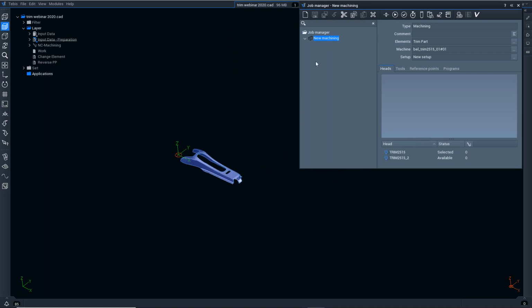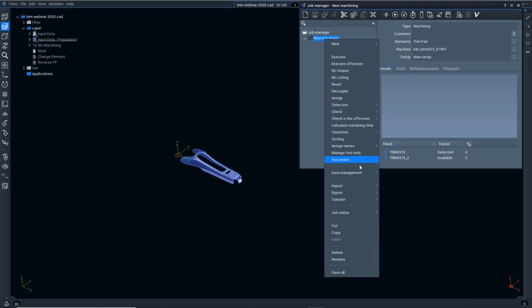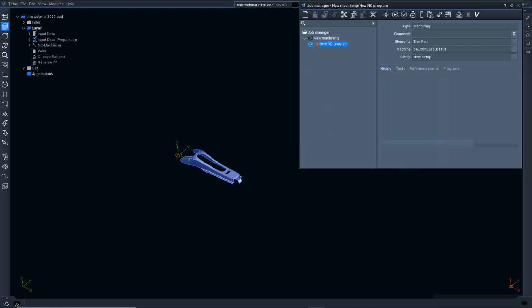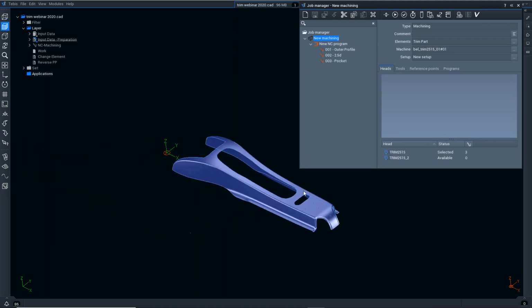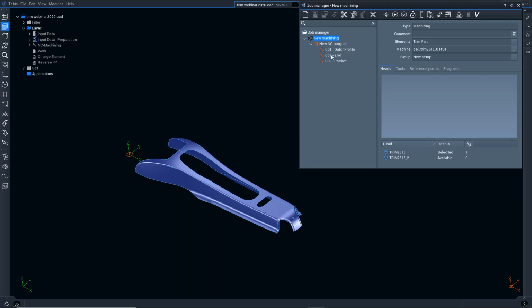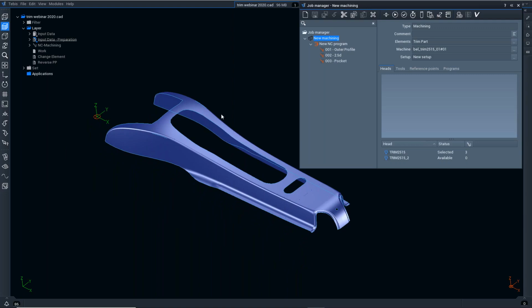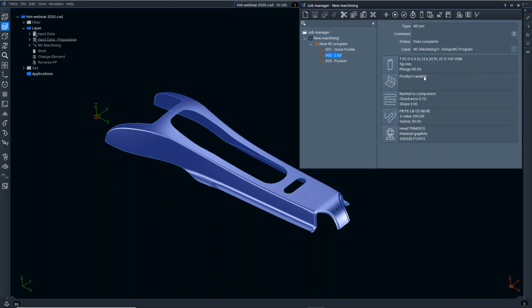What I'm going to use today is a template. So basically all I've done is I've predefined a series of machining operations, which you can see here. And not for the first one, but for the second two, I've had Tebis pre-select the data. So by organizing the data using various colors and positions in the layer tree, I'm able to have Tebis predefine and pre-select the information that's needed. However, in this first operation, I'm going to select the data as I come to it.